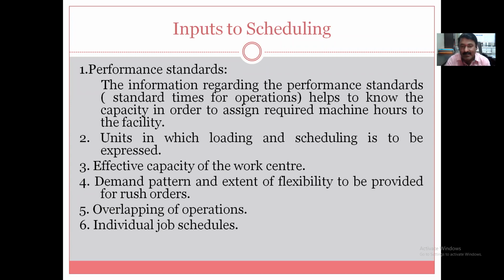Drilling machine, for example, lathe machine, it may take 5 minutes. Drilling machine, it may take 4 minutes. And if you go for some additional jigs and fixtures on the drilling machine, in which 6 different jobs can be drilled at a time, so 4 minutes will be taken, but the quantity will be 6 jobs. So it will not take 24. Again, loading and